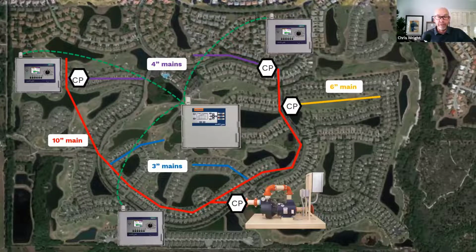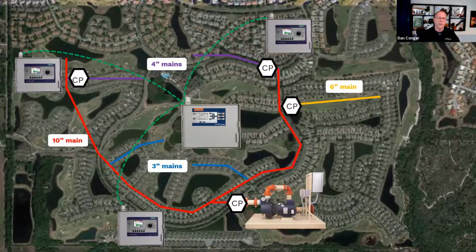Yep. That also comes from the FlowStation, not within the 3200. And so we could say on the 3-inch main, you could open this many valves. We know that it knows the design capacity. On the 6-inch, it's a different capacity. The only thing here is on a main to main, we can't isolate that 3-inch main, because the only way to isolate that 3-inch main is to close the big 10-inch back at the beginning of the pump station. Right. Yep.